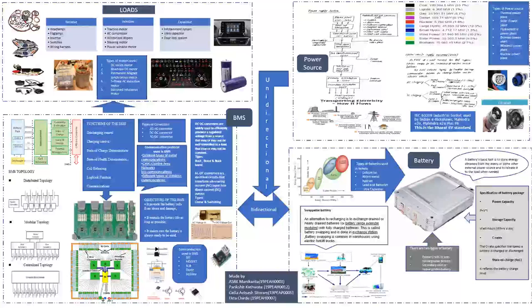Level 2 is used for high rated battery vehicles like Tesla vehicles and Nissan Leaf. The voltage is up to 1000 volts, the power rating will be 30 kilowatts to 150 kilowatts, and the maximum current rating will be 150 amps.